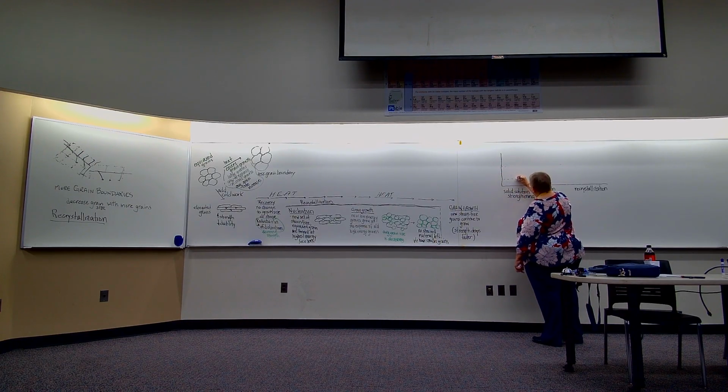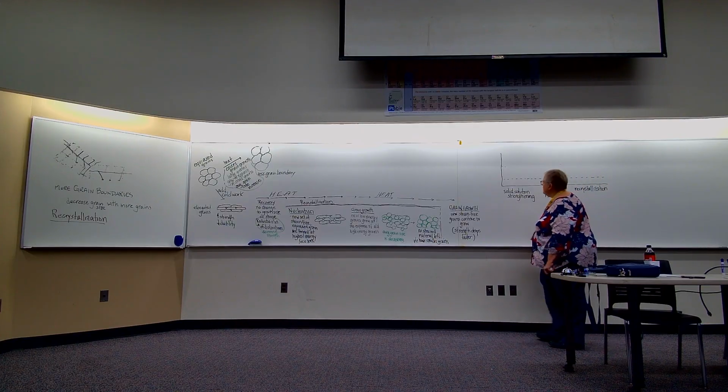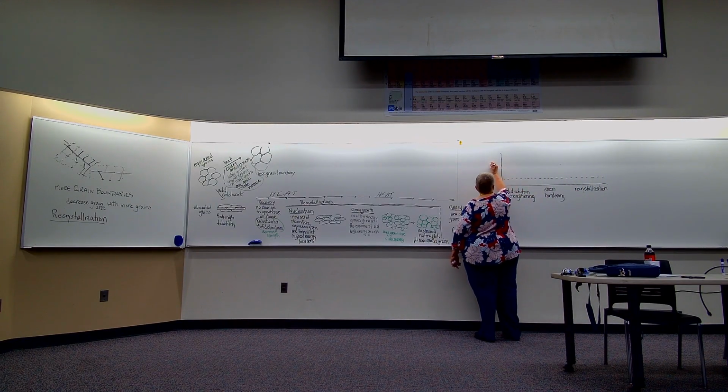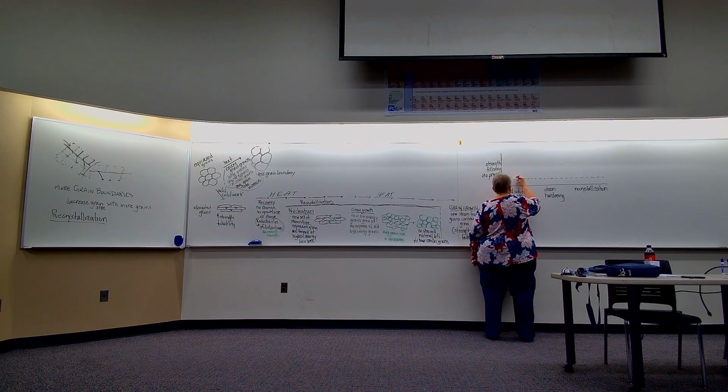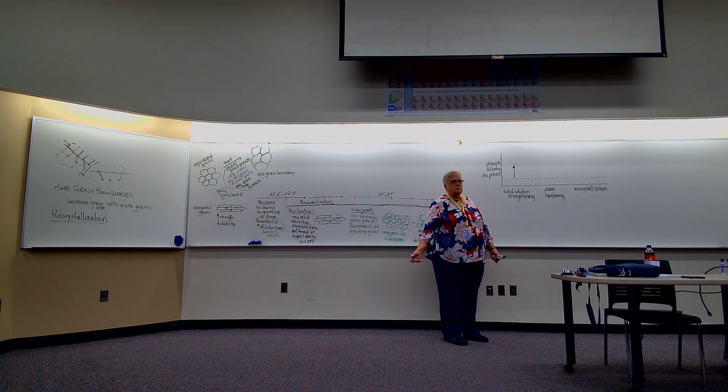If this was my baseline strength before I did the process, solid solution strengthening is going to increase my strength. The extent of the increase is related to the percent of that impurity atom that I'm adding.